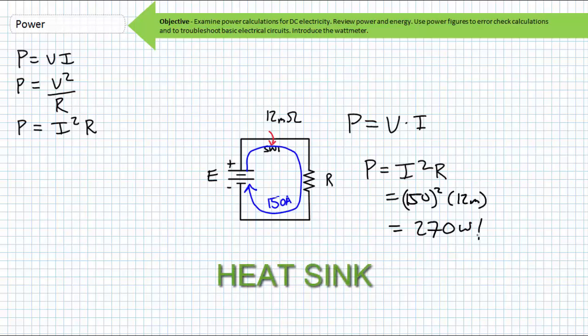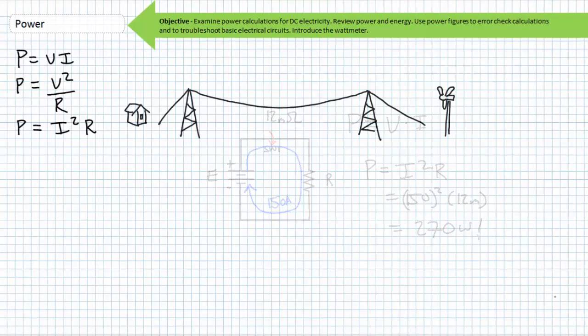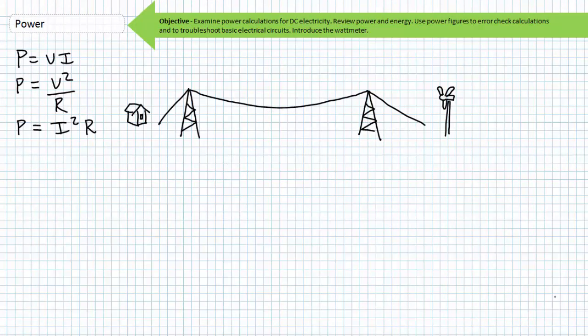A heat sink is a piece of finned aluminum or other heat-tolerant metal simply used to dissipate, in this case, 270 watts of power loss just in the switch. If that heat sink wasn't there, the transistor would just melt and be the source of all sorts of bad. Sticking with this topic of power losses associated with different magnitudes of current, you'll immediately appreciate the reason why electrical